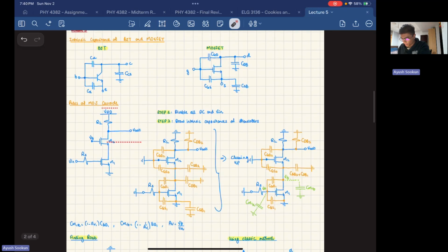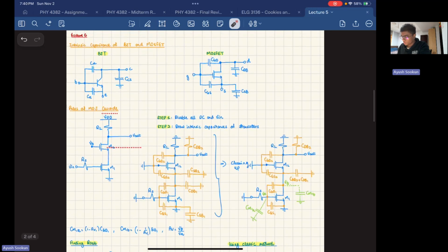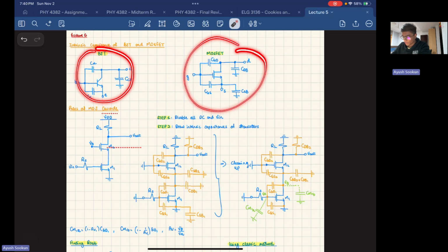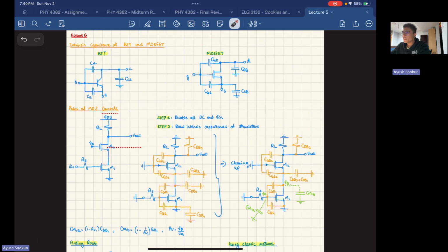Oh my God, burping. Okay, so we got these two scenarios here, the BJT and the MOSFET. If you look at a MOSFET or a BJT, for example, you have a PNP or an NPN. At the boundary of the PN junctions inside of the PNP, you have an electric field. Same thing with the N and the P side, you have an electric field there as well.